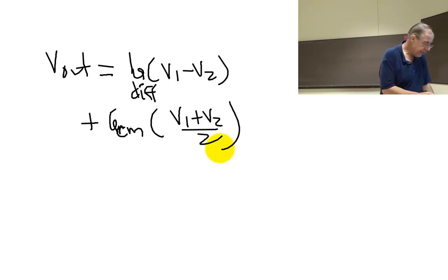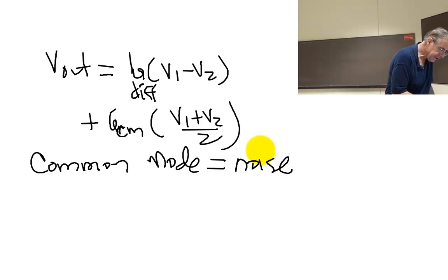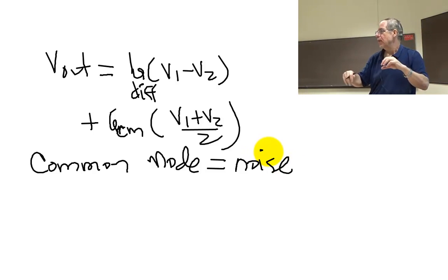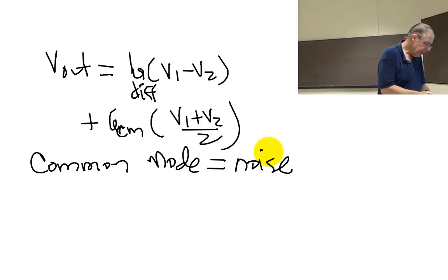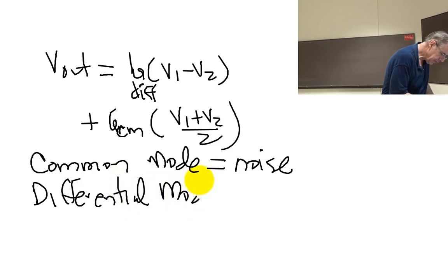And typically, the common mode signal is noise. For instance, in your electret microphone, in sound, what does the average voltage mean? It doesn't mean anything, it's not signal. It's crap. We want to get rid of it. And typically, the differential mode is the signal. Okay?